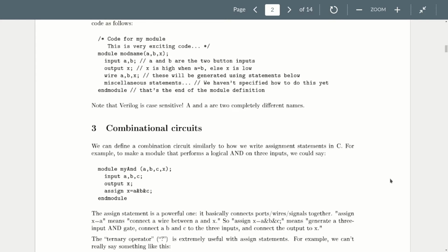So this assign statement says the following. Let's take A, B, C, let's AND them together. Well, how do you build hardware to do a logical AND of two things? You make an AND gate and you feed the two things into the input. And it actually understands that I'm trying to AND 3 things here, so we'll actually configure a 3-input AND gate.